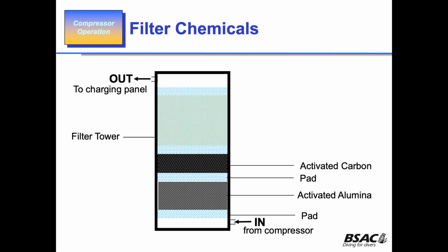So up to now we've got one set of moisture removal. Then we go to a pad, then to taking out impurities. It takes a bit of oil out, and it also takes out some particulate matter. Then we go up a bit further through another pad, and we come up to the molecular sieve. Now, molecular sieve, again, is good for removing moisture.